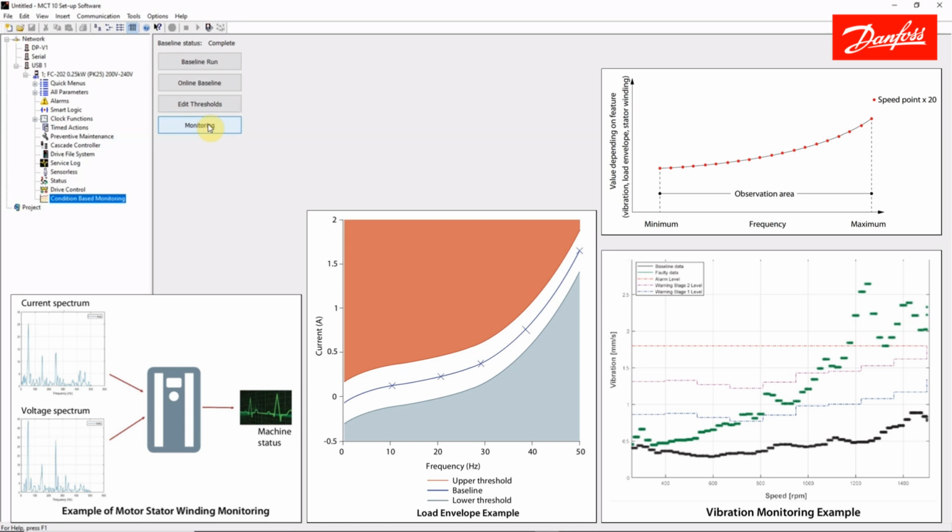In a pump or fan application, it's likely to expect that we can sweep the speed range in rather short order, maybe as little as a couple minutes, while in an application more related to an industrial process, we'll need to understand that process a little bit more specifically and recognize its general limits for speed and load. Knowing that, we may find that it takes a significantly longer period of time to record that data, maybe up to as much as 6 months.